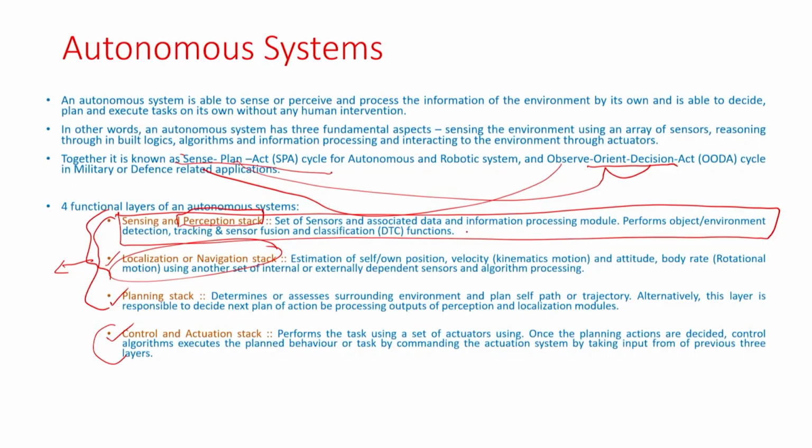Sensor fusion is when you want to track the pedestrian using, say, an FMCW radar plus a camera. With both you are tracking the pedestrian. Now, you want to fuse both data together. That part is called fusion, in an optimal way, to get better information about the pedestrian. Clear? So, this is your perception function, what we will be talking about.